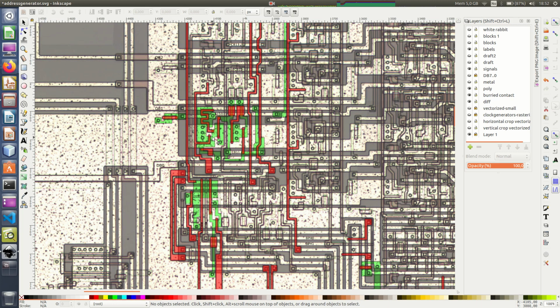The reason it's enabled is because this long net up here can pull it to ground, and when it pulls it to ground, it can't put any zeros out on that bus. It's a wired OR thing.